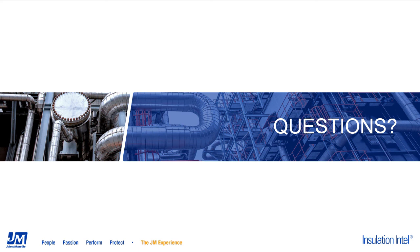All right, Scott, you can take a quick break. Jim, this next question is for you, and that is, what is the 1/2 inch safety hem used for? It's designed to help prevent cut injuries from installers or people handling the jacketing. For aluminum, it's not so bad, but the edges of cut stainless steel jacketing are near razor sharp. So some people like to have a 1/2 inch fold on one edge, so that's the edge that on the jacketing will be ultimately exposed. And by folding that under 1/2 inch, you eliminate the sharp edge on that particular edge.